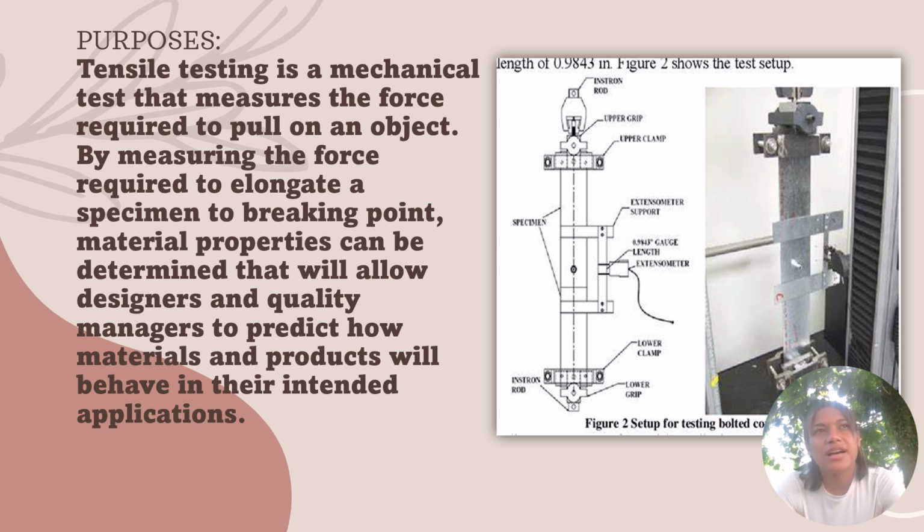The purpose. The purpose of tensile testing is a mechanical test that measures the force required to pull an object, by measuring the force required to take a specimen to its breaking point. Material properties can be determined that will allow designers and quality managers to predict how materials and products will behave in their intended application. So Figure 2 shows the test setup.